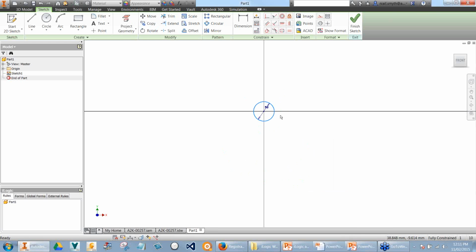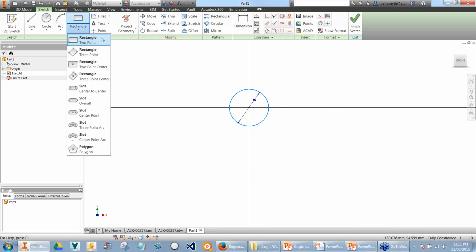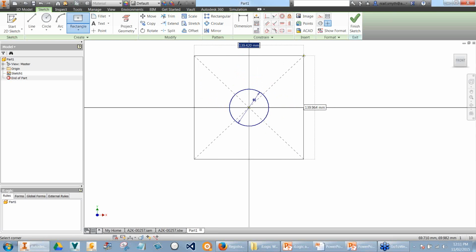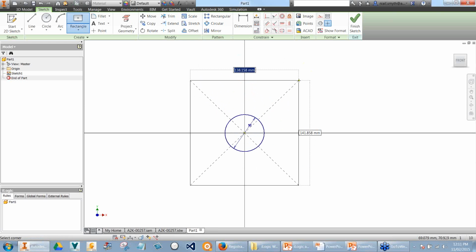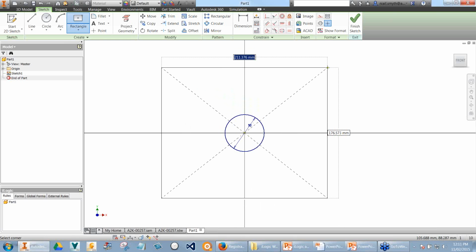Okay, so that's one part of our initial assembly that we're going to work with, and we're going to use solid body modeling as well. Solid body modeling is essentially creating multiple parts within one part file. As I'm creating a center point rectangle, I'm going to type in the name of the parameters.